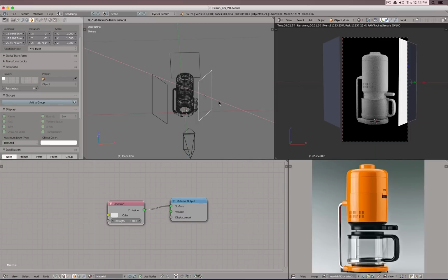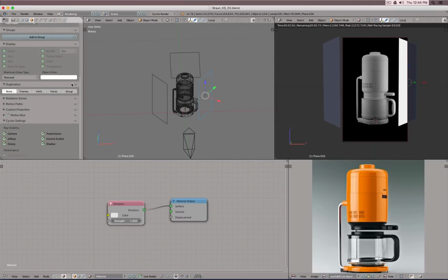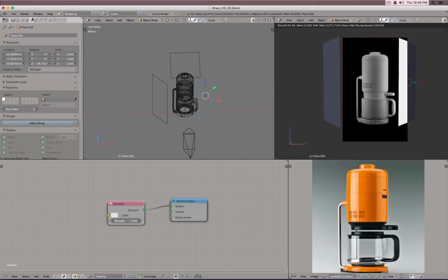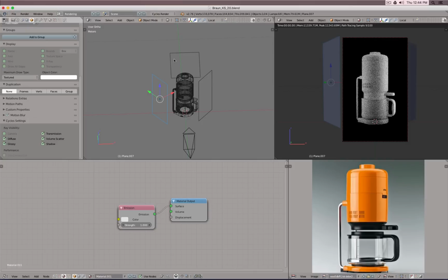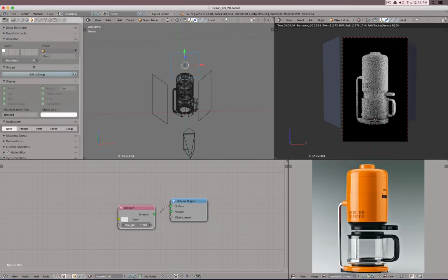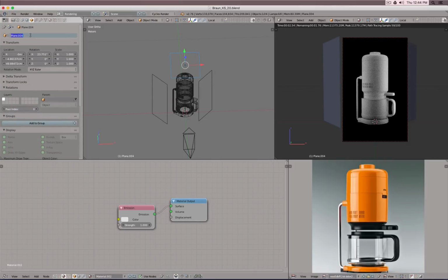Two things we want to do. So on purpose, I moved this light actually in. And maybe this light actually I would like not to show up in my rendering. So you can click an object. You go to the object properties. This is, for example, the right light. And then we turn the visibility for the camera off. Same here, same there.